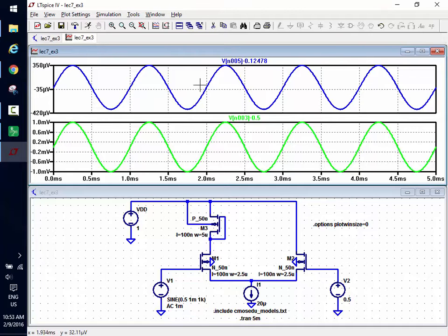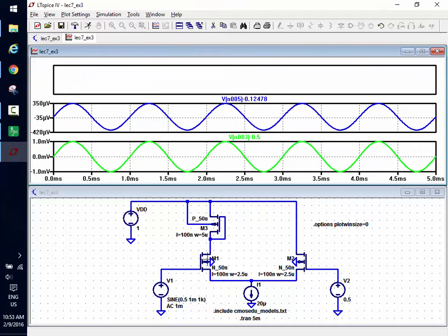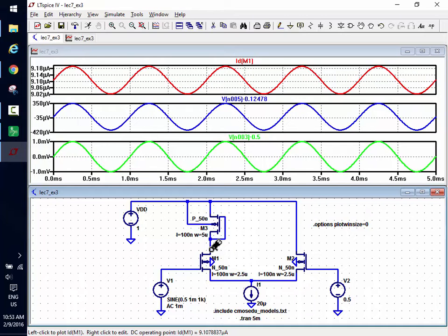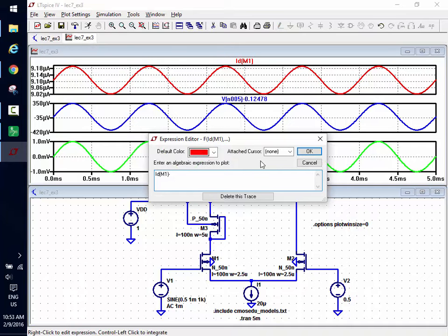Current. So I'm going to add a plot plane. Then I'm going to plot the current. But what do I expect I'm going to see? I'm not going to see AC plus DC. So what do I do to see my 75 or 80, whatever it was, nanoamps? I'm not confused. My AC is riding on DC. I don't have magical AC without DC. I'm turning the faucet back and forth and looking at the wiggles.